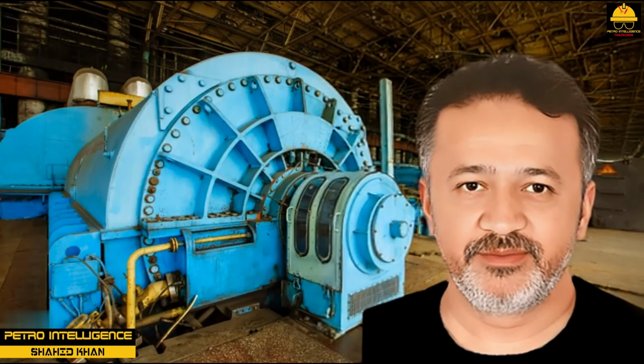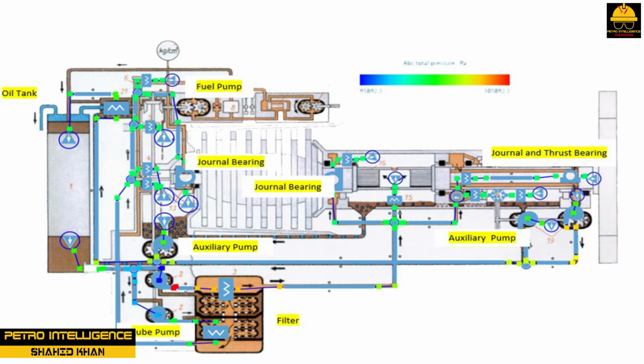Lubrication system. The lubricating oil has 5 functions. It lubricates bearings and gears. It cools the lubricated parts. It transfers frictional heat. It acts as the hydraulic medium for the governor. It acts as the hydraulic medium for the actuation of the governor valves and safety devices.